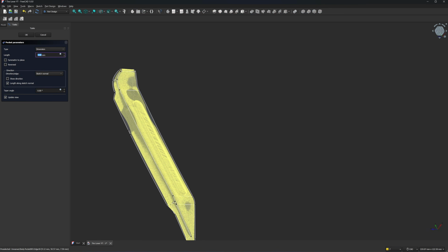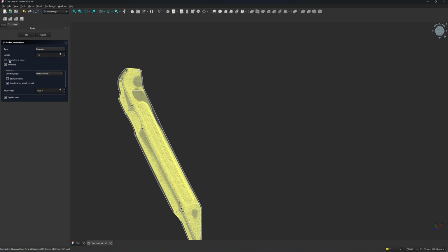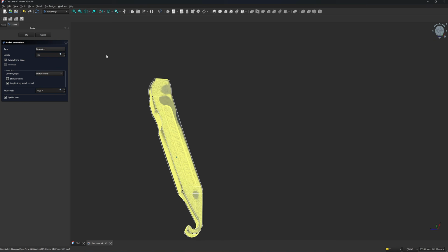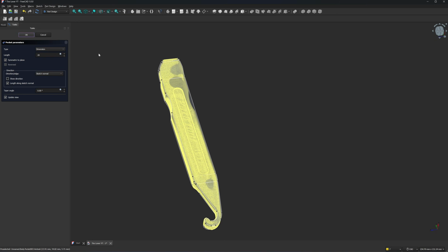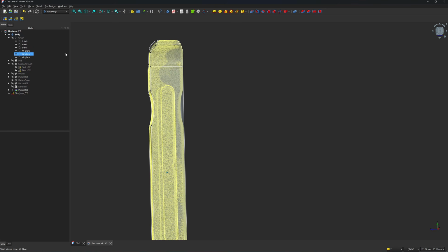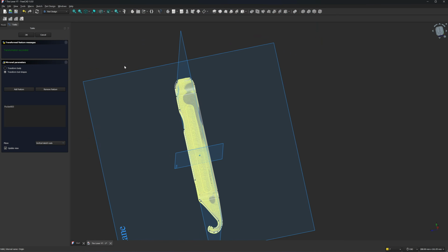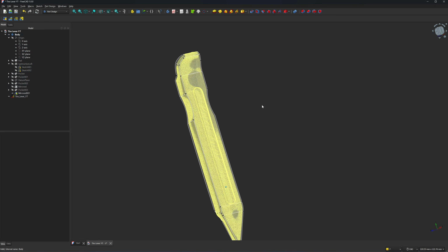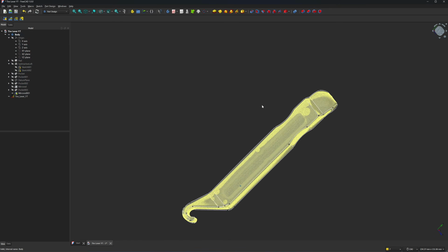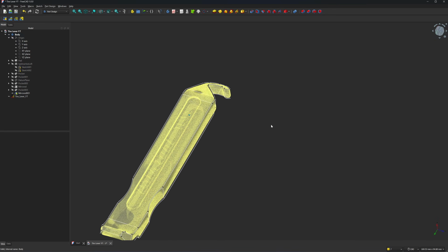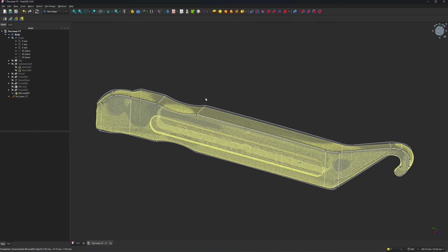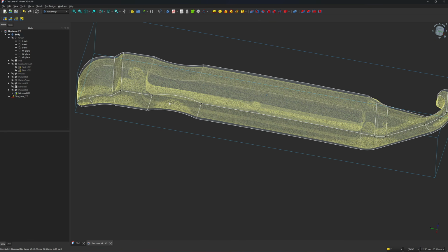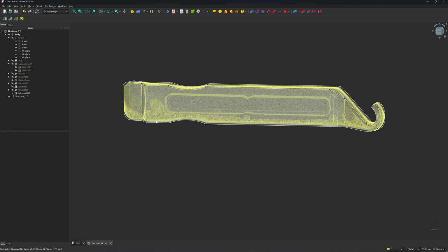I'm gonna cut it to like 15 deep cut, reverse, symmetry, okay, 20, okay, now I cut one half, click on OK. Next I'm going to mirror this pocket command using this, and I'm going to use the XY plane, click on OK. Alright, now I'm getting used to FreeCAD. This is I think my 7th project in this channel. So you probably need support for this, but I don't mind.